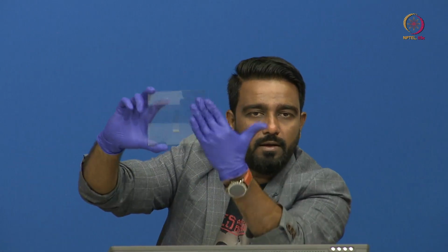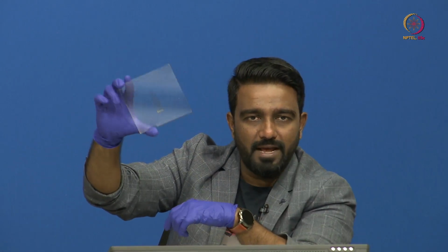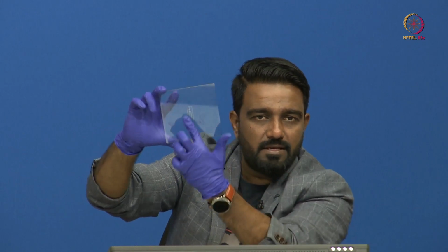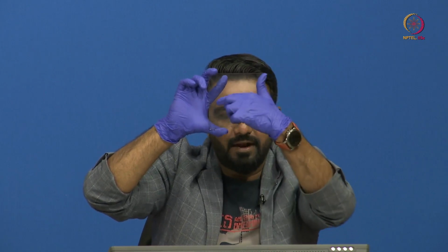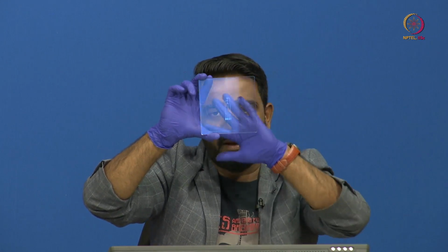You see, you can see the area transparent, right, and then there is something in the center. You see, there is something in the center and the remaining area is transparent. What is this mask? Bright field mask. The field is bright, the pattern on the mask is dark. Bright field mask, easy, right. What is the size? It is a 5-inch mask. For 4-inch wafer we have to use 5-inch mask.